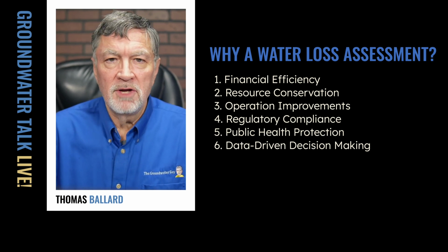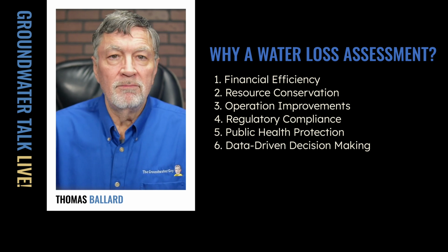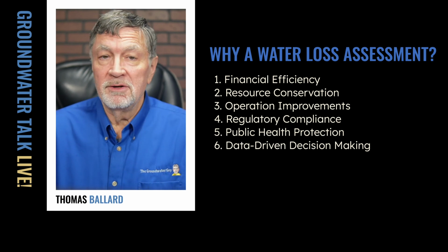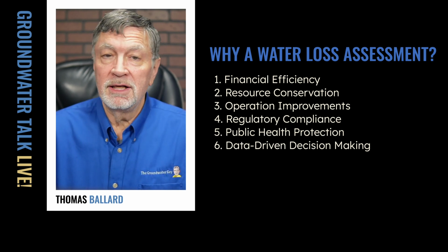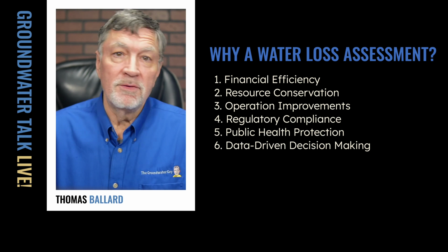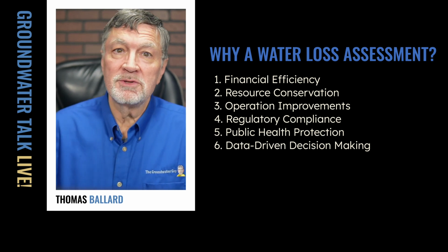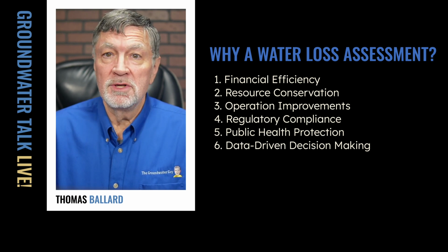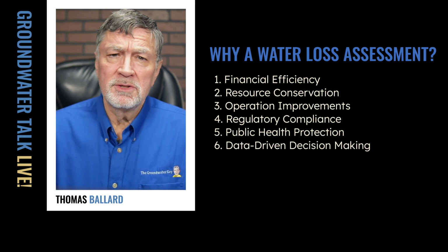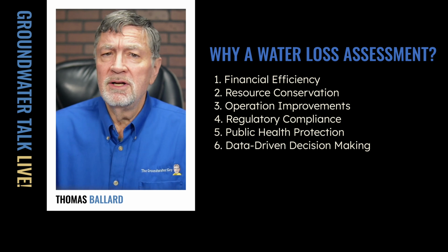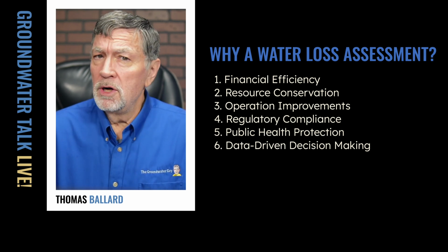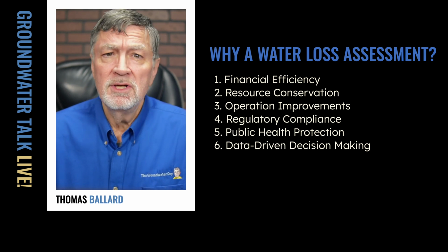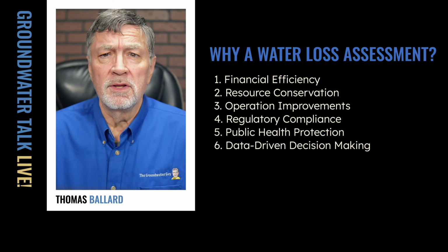But resource conservation is another reason. If you're pumping water from a well and having to work that well over time to produce water that you're then losing through a leak, for instance, or theft, then that's going to deplete your resource. It's also going to be harder on the pump, because you're going to work that pump and that well harder. You're going to have to maybe replace it a little earlier or do more maintenance. And so the costs are going to be higher for you there.